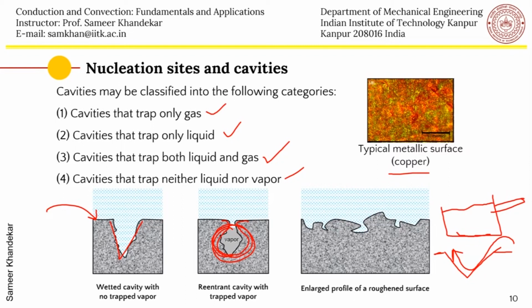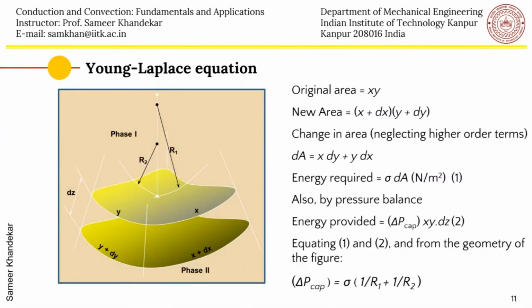Before we proceed to understand how a bubble actually forms and then subsequently grows on the surface, let us first try to understand the Young-Laplace equation, which you have also studied in your earlier years. Whenever a surface is formed, that's an interface between a liquid and a vapor, for example, because of the existence of that stable surface, it comes in equilibrium because there is a pressure difference which it sustains across it. So this is a very simple mechanical way of understanding.